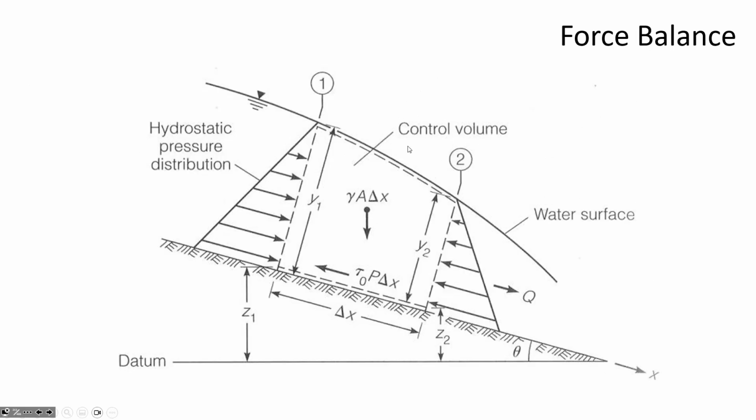So last time we looked at a cross-section of water that was experiencing non-uniform flow. Remember, non-uniform flow is when the velocity is changing in the direction of flow. So here, since the depth is decreasing, what that tells us is that V2 would be greater than V1. And that makes intuitive sense to us that the water is speeding up as it's flowing towards, I don't know, a cliff. Something's causing it to accelerate in the direction of flow, convective acceleration.